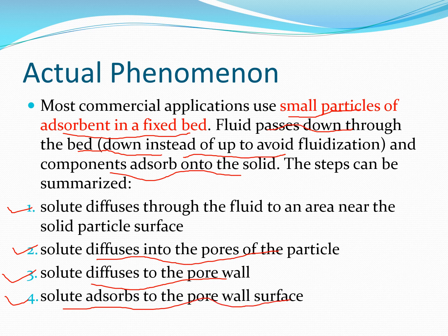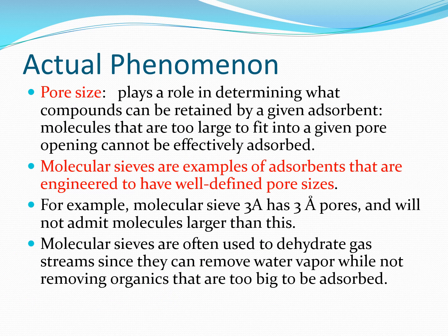So this is the basic explanation of what is actually happening. How the molecules move is basically an application of mass transfer and the law of diffusion. The molecules first travel from their bulk body and move towards the interface, and then from the interface they move towards the solid surface, and then from the solid surface they are retained at the solid and then move inside the pore, and then are retained at the pore wall surface.